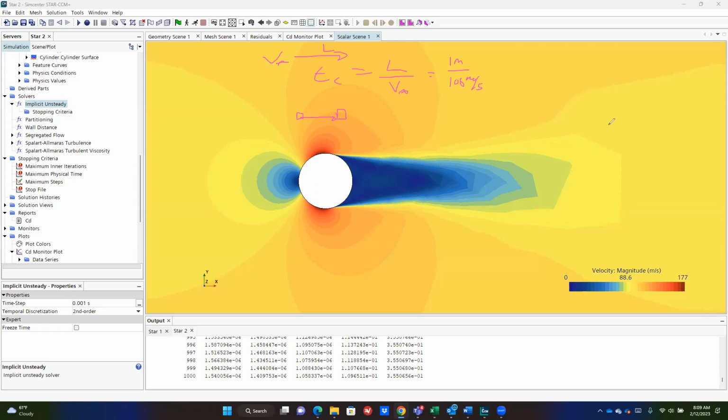That is 0.01 seconds. And we typically divide that by 20. You want at least 20 time steps over there. So we end up with an estimated time step of about 0.005. So I'm going to use that here, 0.005. Oops, I missed a 0.